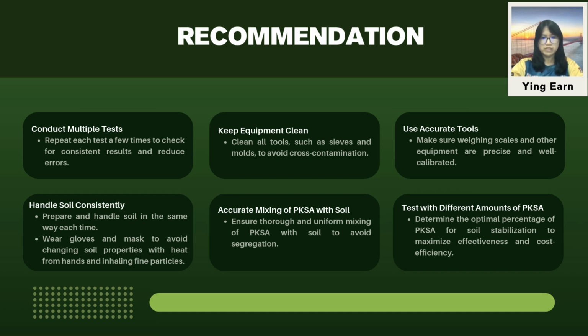Besides that, we must use accurate and well-calibrated tools. For example, we must make sure the weighing scales, sieves, or other equipment are precise and well-calibrated, as errors here will affect the entire test outcome. Moreover, we should also handle the soil consistently throughout the testing process.